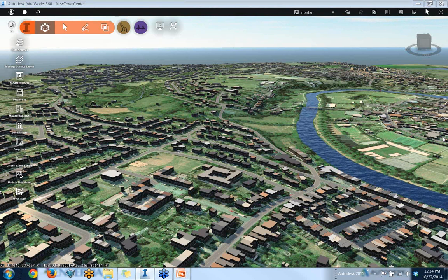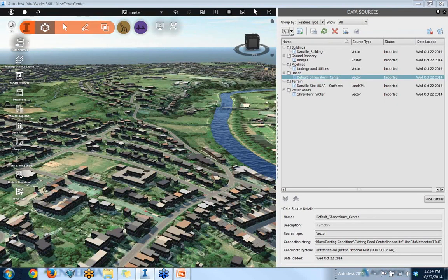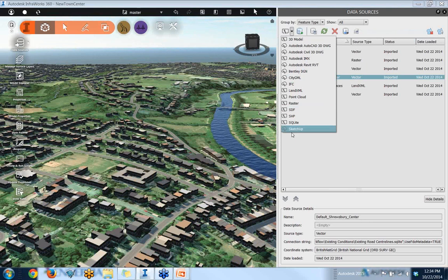Then I see another one. It says the data being used is in formats that local cities in Texas don't give. Would you do anything different with a SHP file? No, actually the whole idea, the reason I said it's okay with doing it with this data, at first I was reluctant to do it with this data because most people in Texas are using shapefile data, but configuring it, importing it, all that, the whole concept there, it's all done the same exact way, whether it's a shapefile, SQLite file, LiDAR file, or whatever those files were in my data sources list. In this data sources list, all these files get configured in the same manner. Okay?